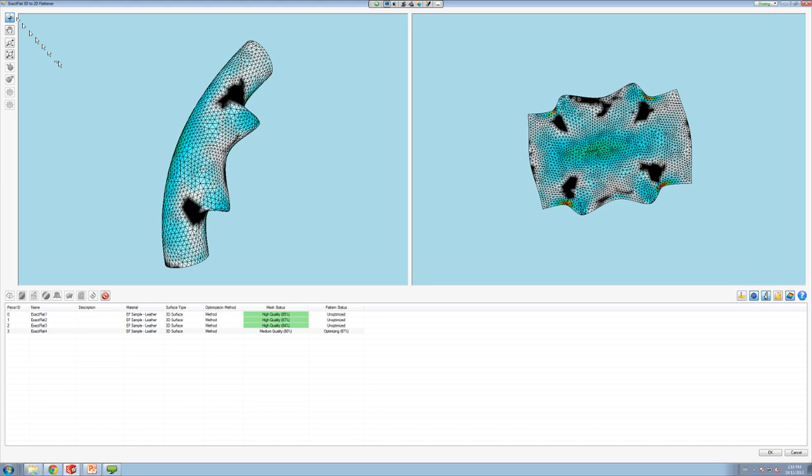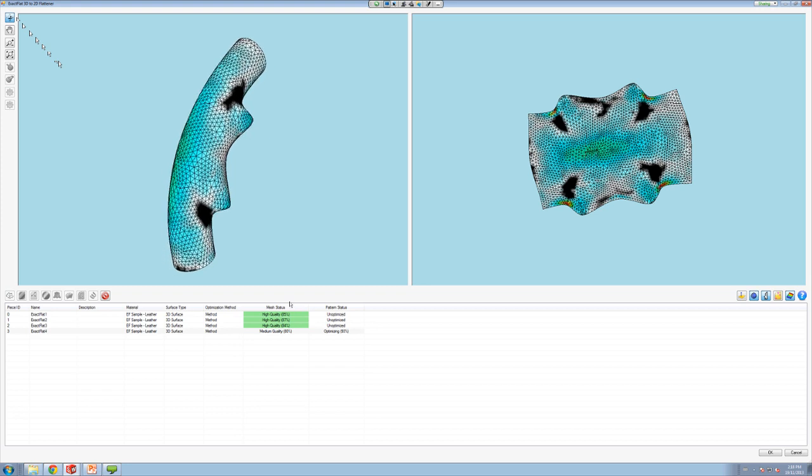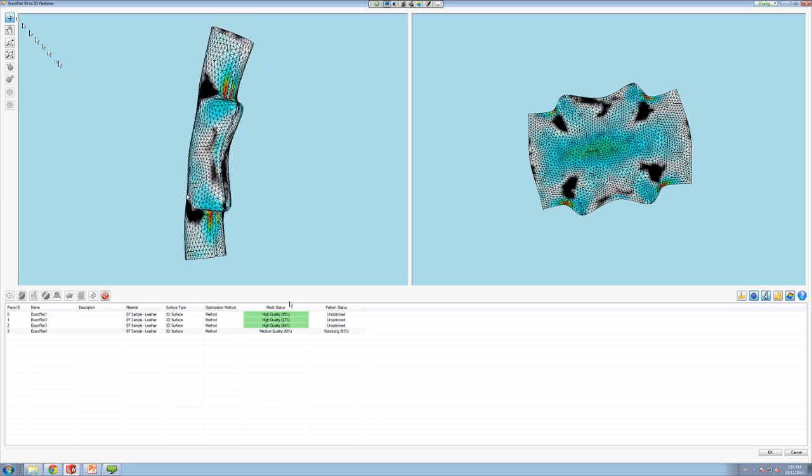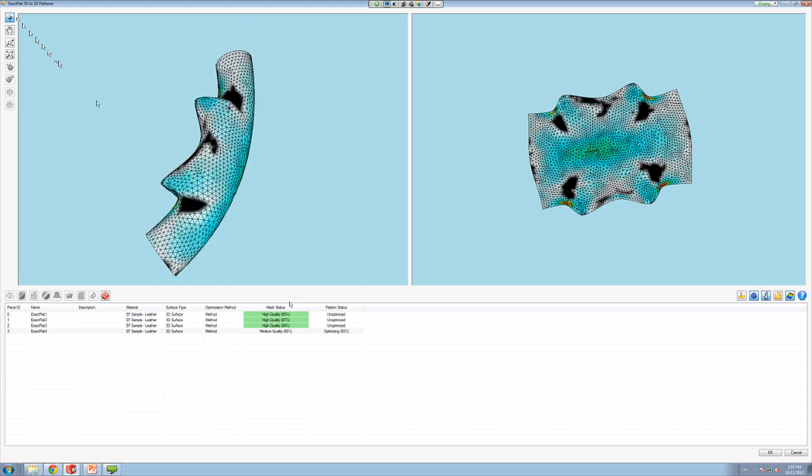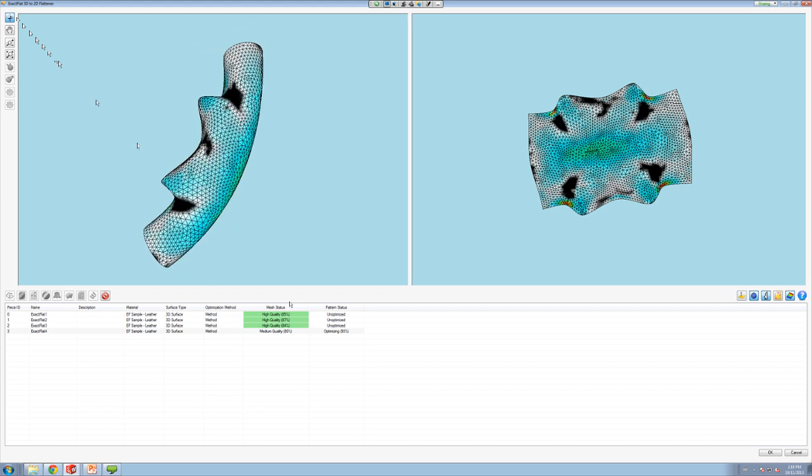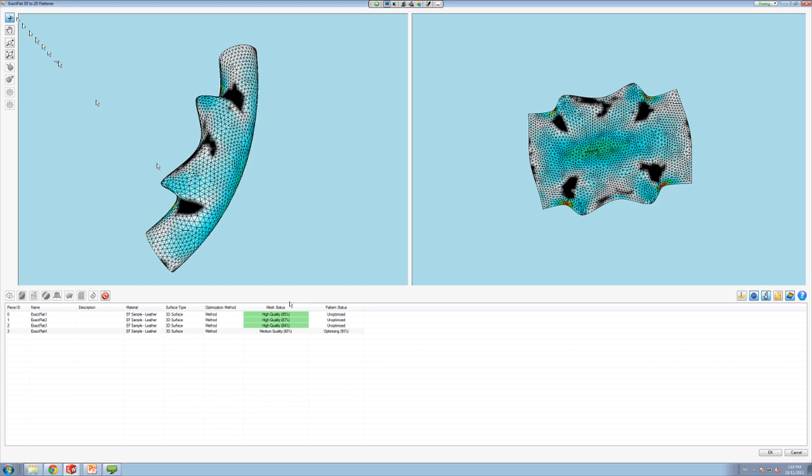You would have a different pattern shape at the end and a different overall perimeter geometry. Once the algorithms start, it does a search for strain and sag, and it tries to eliminate that strain and sag. And it does this through an iterative process. If it finds it, it reshapes the polygons, and we have a new candidate for a flat pattern.